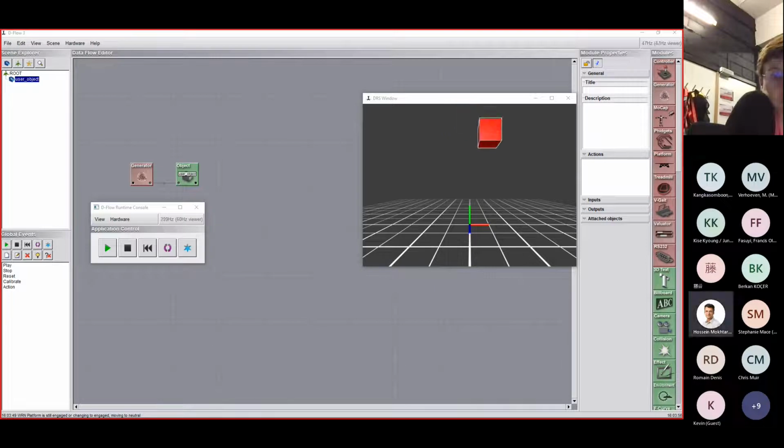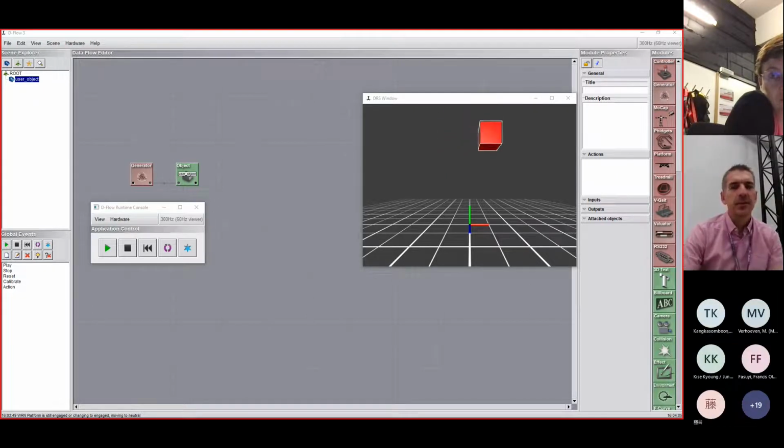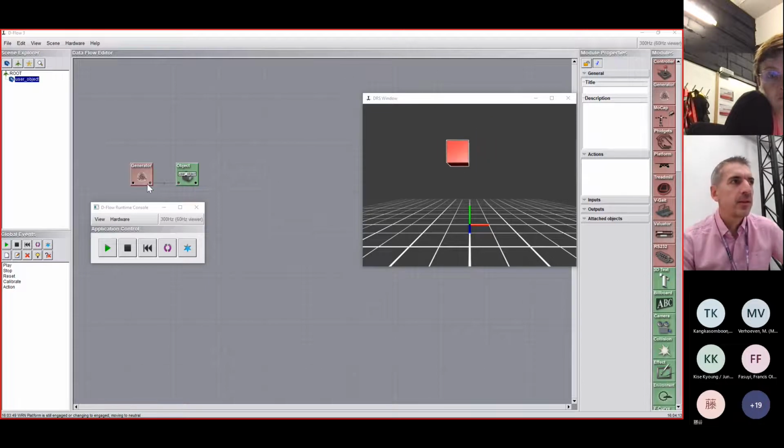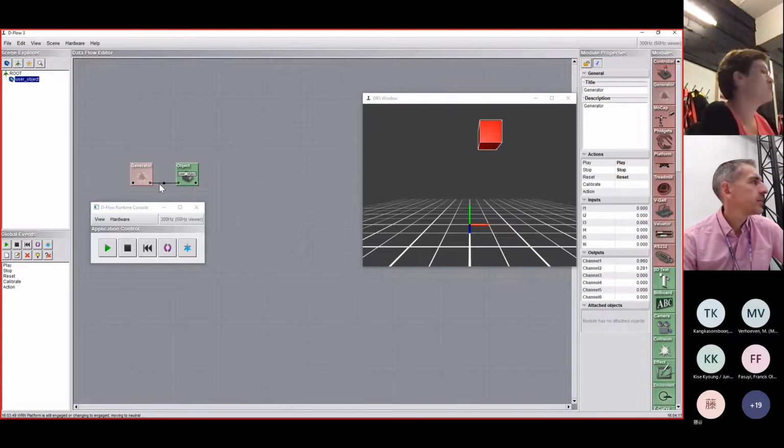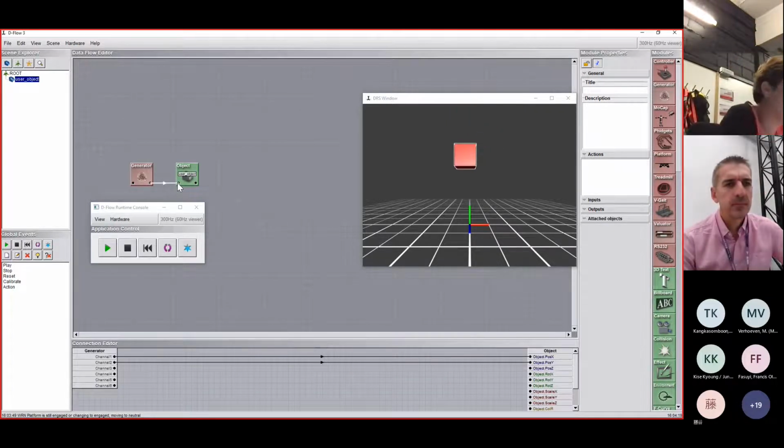Someone has a question? Yes, Romain, please go ahead. Unmute yourself and ask your question, please. Sorry, thank you. The object doesn't move when I use the runtime console and press play. Did you connect it like from here? When you click on this line, there should be a connection from generator to object.